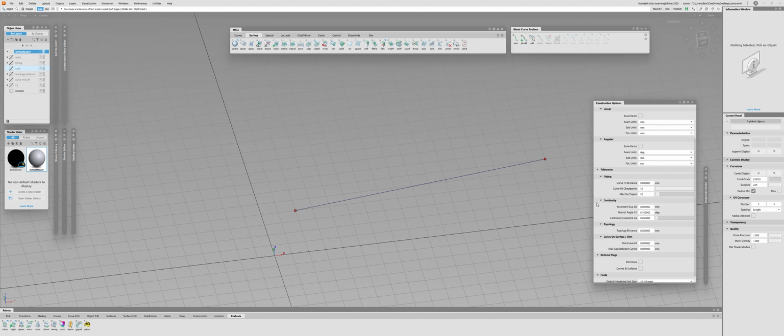And another extreme is really small stuff like jewelry. So if you're talking about jewelry, the positional continuity can be even smaller. It can be like 0.0005, and the tangency can be 0.001, and the curvature can be 0.001, so 5 times tighter than consumer electronics. But once again, it really depends on the type of jewelry. Is it real jewelry, or just some fake stuff, right? But once again, these two, the super big ones and the super small ones, are really extreme.